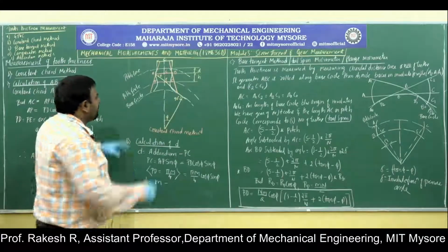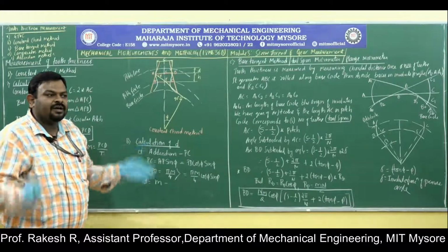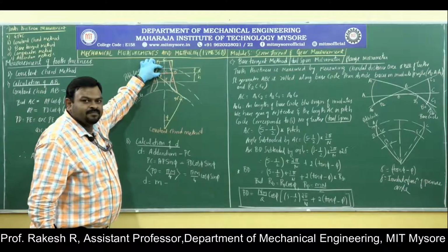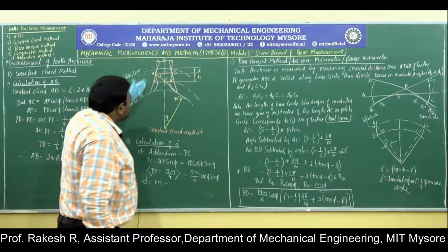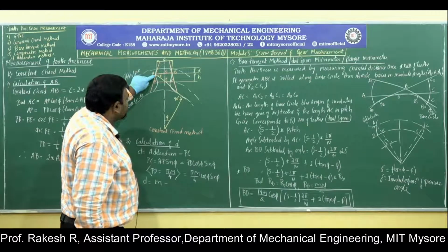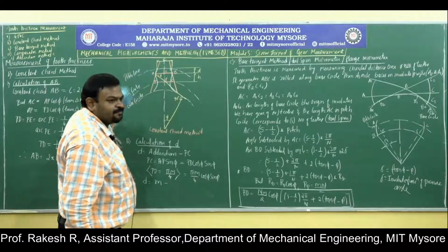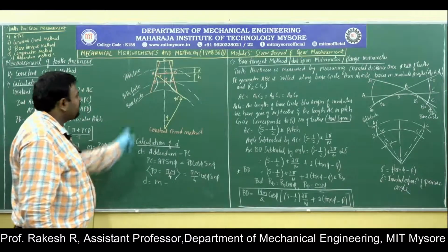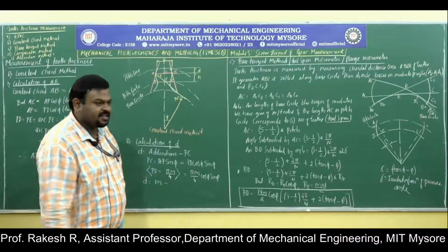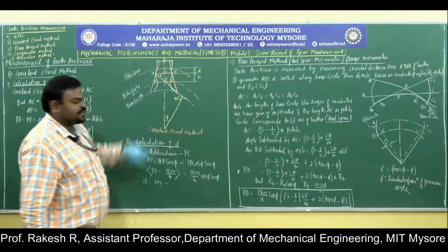Before that, first I will draw two vertical lines. These two vertical lines make the chord constant. This chord is constant, this part is constant. After insertion of these two saffron lines, then I will mark a point A where this line intersects the flank. Similarly, B, this line intersects the flank edge of the teeth. After that, I will be extending this line up to base circle.